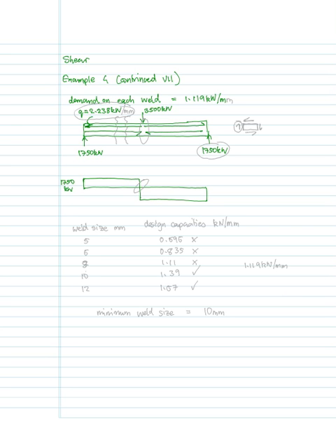So these aren't bending stresses. They're shear stresses or shear tractions, and you can see at the center of the beam, the shear would be 0, and then it would switch directions, so that the tractions would switch directions at the supports.